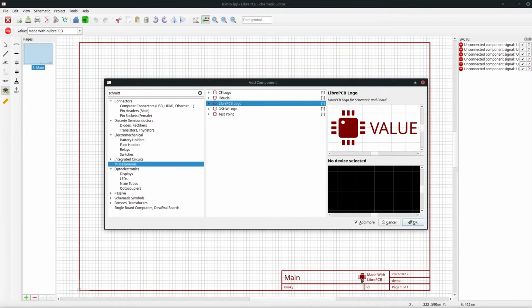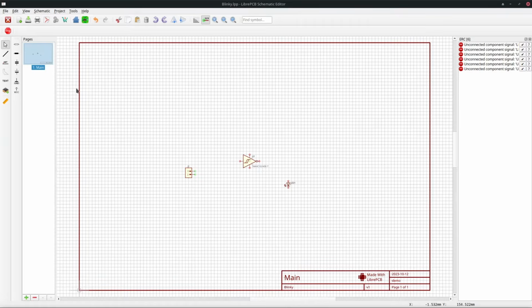Resistors and capacitors can be found in this dialog as well, but they are also available directly from the toolbar. Press the tabulator key to move the focus into the capacitance field and type 100U for 100 microfarad. Or 10K for 10 kilo ohms.